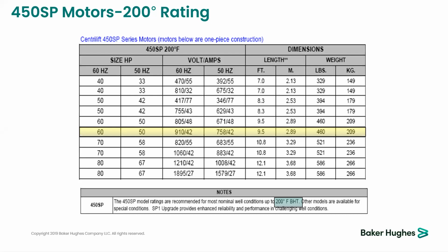Normally, in terms of selecting the motor, you have to go for the higher volt, low amp. The best practice is to select the higher volt, low amp. So almost always go for higher volt, low amp. Don't go for the lower volt. Why? Because the higher volt will give you a higher torque that will eliminate the stuck during startup, or if you have any stuck during the operation, it will give you higher torque, which will allow you to free your pump from any stuck.